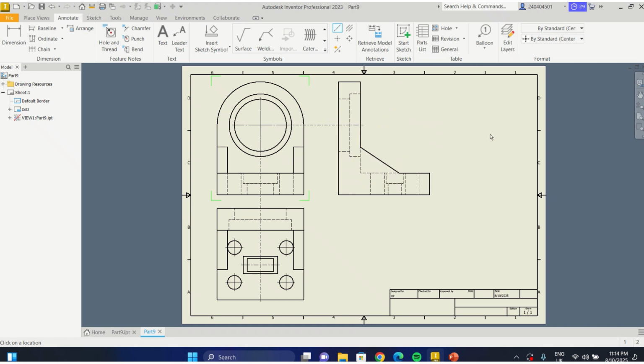Then likewise for these circles, it should actually pass through this to show that this is the center line. So you can do likewise. Just come here, click on this center, and then on this. It may not work because it's joined with other objects, so just make sure you push it through.